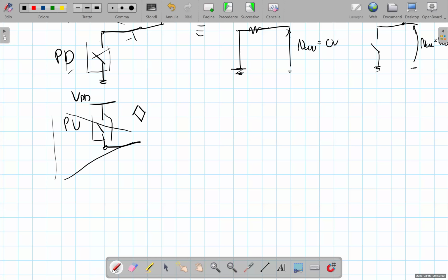The complementary case, in which we have just the pull-up network, is less frequent. The open drain gate is then suitable to force just the output high. When we have to force the output low, we need to add a pull-down resistor, which, when the pull-up network is not active, forces the low logic state.